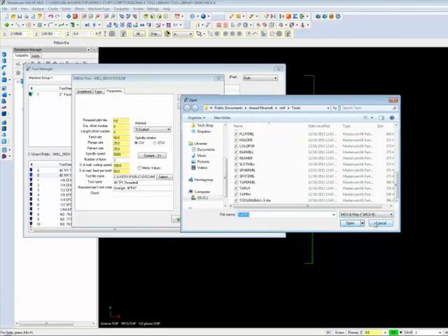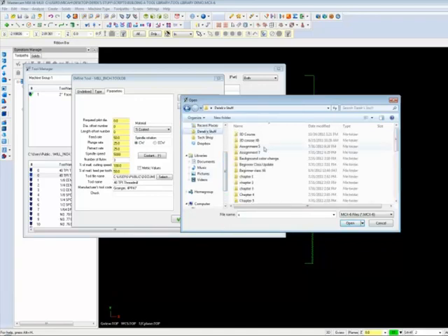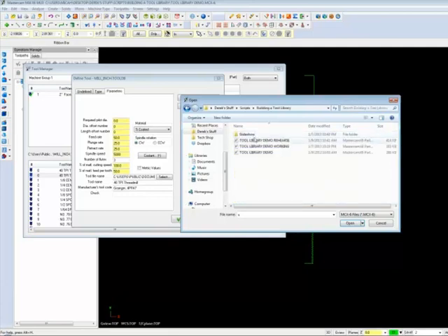Also, where it says file name, when it's highlighted, if you know the beginning of the tool name, say it's a spot drill, if you put S, it'll show you a list like that. See how it does at the bottom. So if you know the beginning of the name of that tool defined, that geometry, it'll come up real quickly. Is it down the list below? But did you create this file as a separate file? Yeah, I could probably. You put it somewhere else. That's fine. It still works.